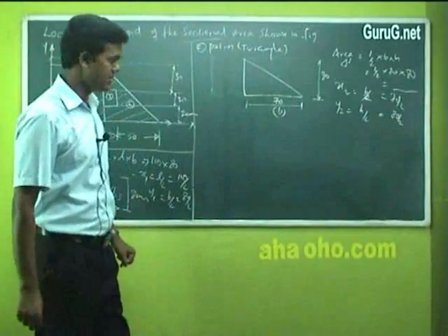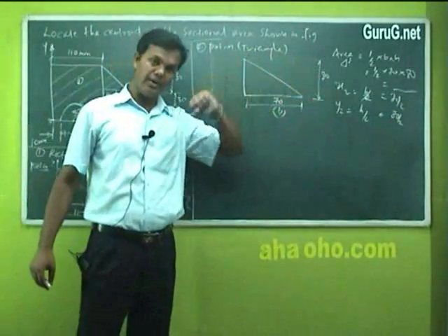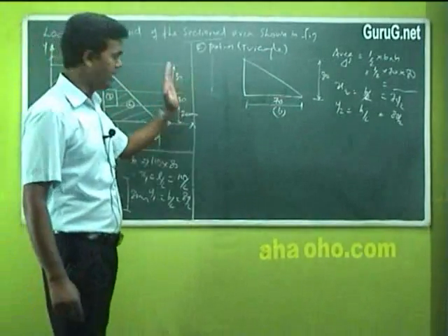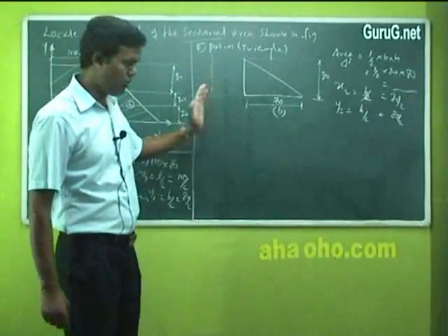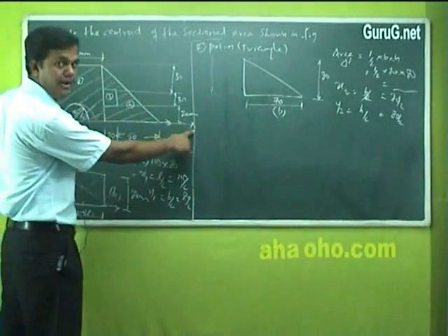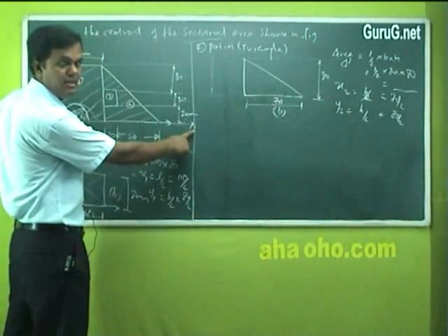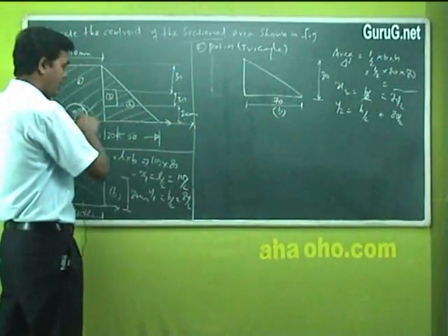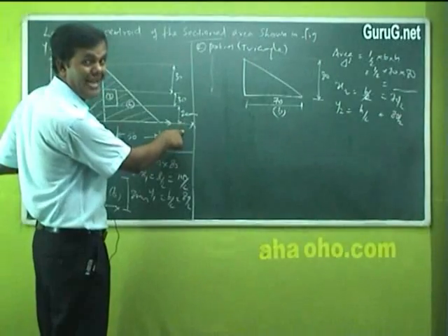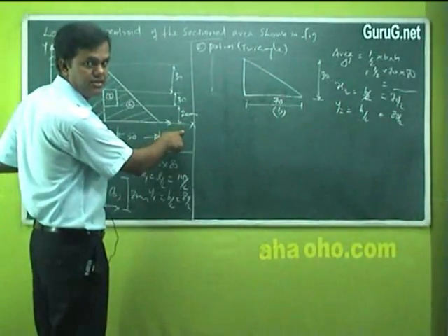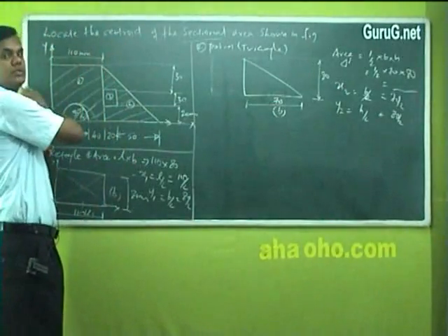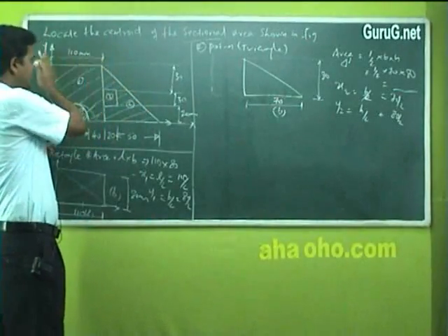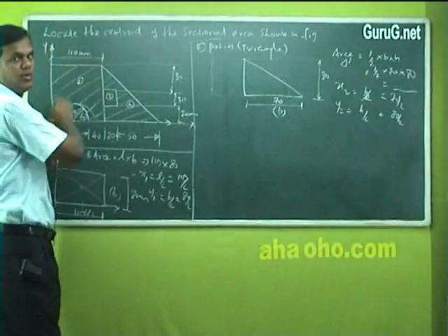But the one change is this: x and y we are calculating starting from a reference point. Any problem, any diagram given, first we fix the OX, the common x base axis. I can say the bottommost line of the whole sketch becomes your OX, the common base x axis, a reference axis, and OY is the leftmost line of the diagram. Whatever different sketches may be clubbed together, the leftmost edge is called your OY line.